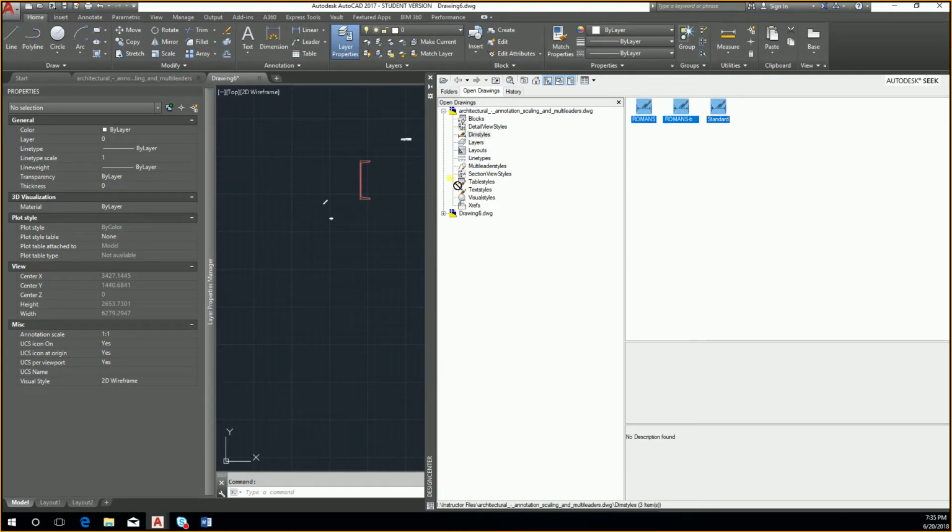Dimension styles can be brought in the same way. Line types, the same thing, and so on. So all of these things are standards that were part of a different drawing package, but I can now make them part of my drawing package right now. It doesn't let you do blocks. The blocks I do one by one, but all the layers and everything else you can do.